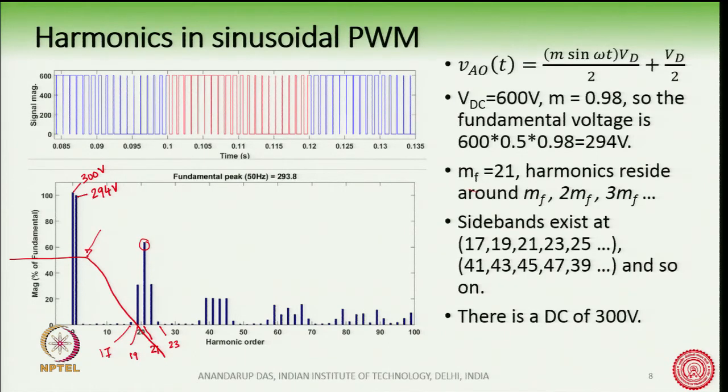If we choose the corner frequency in a clever way, then we can make the gain plot in such a way that for all the harmonics here, the gain is 0 or less than 0 at the harmonic frequency and at all the higher harmonic frequencies. Therefore, the filter will get rid of all the harmonics present.